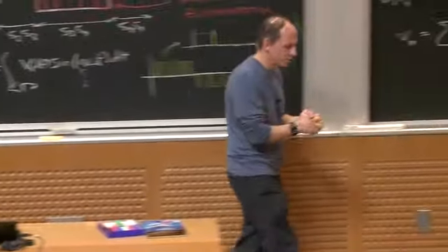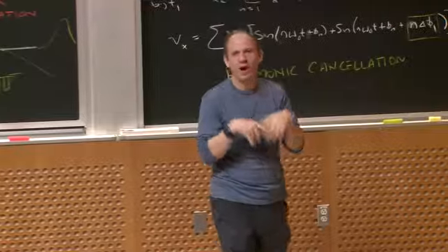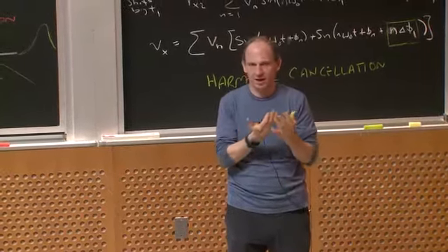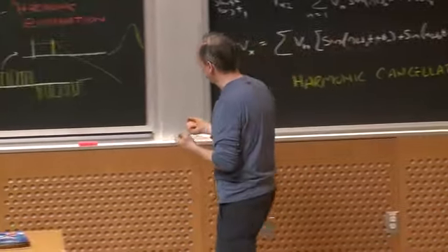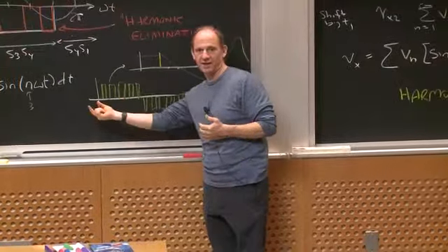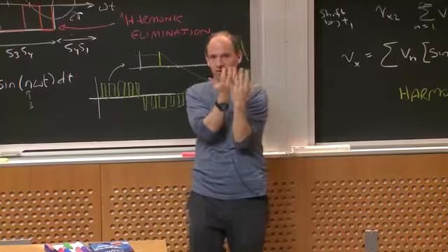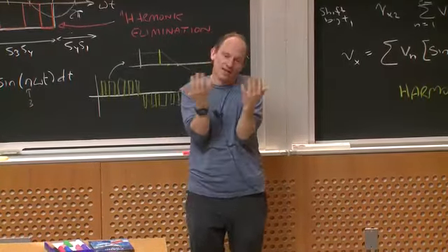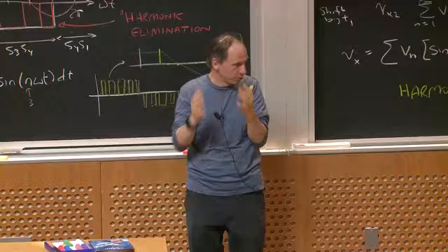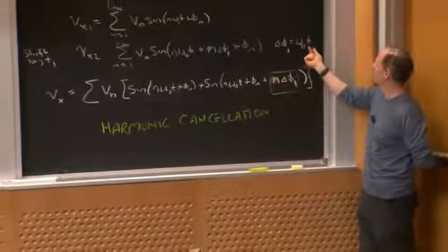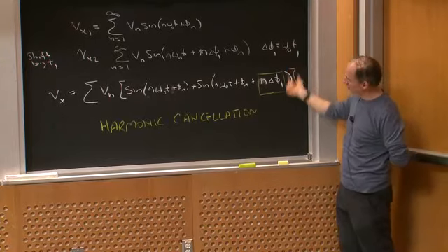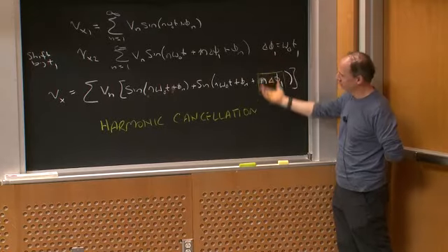Yeah, I wouldn't worry so much about the wires heating up, but your broader point is a good one. I'm kind of limited by timing angles with this guy, how much I phase shifted. If I don't control that very well, if there's delays between the circuits, depending upon how much absolute time that is, this harmonic cancellation is limited by how accurately I control that T1, right? So I want to be very good about shifting this the right amount.